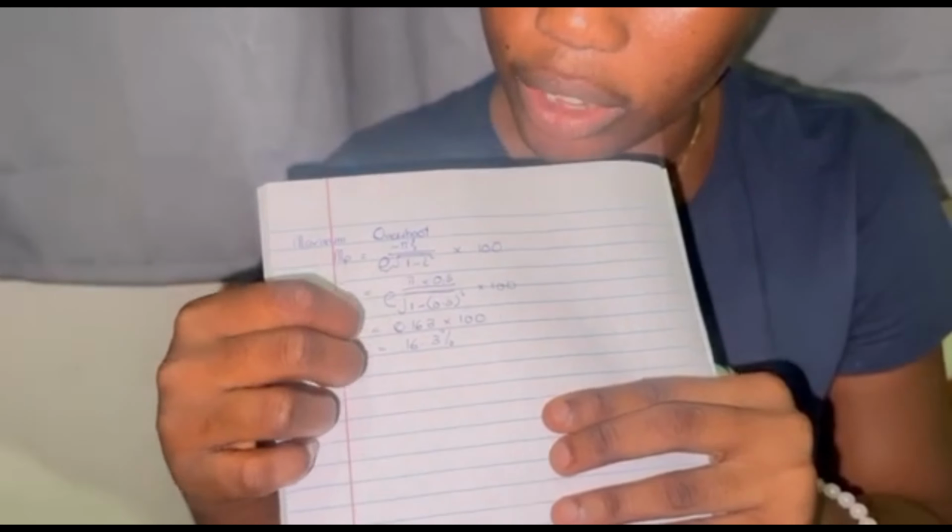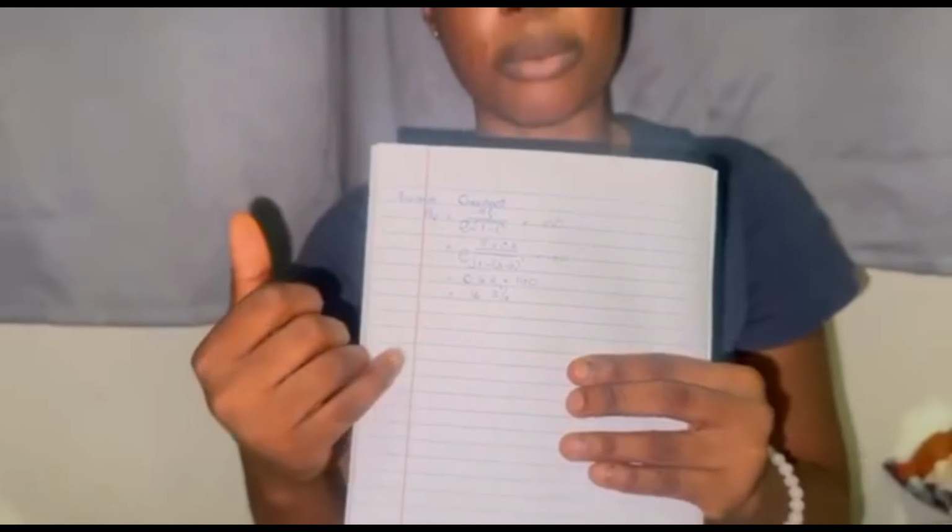I'll be taking you through the last question, that is finding the maximum overshoot. We have a formula: MP is equal to e raised to the power minus pi zeta over square root of 1 minus zeta squared, times 100. Zeta is the damping ratio, and in this question zeta was given as 0.5. So as you can see, we fixed the 0.5 into the formula, where we got our answer to be 16.3%. This means that the system output can exceed the final steady state by about 16.3% before finally settling back to its stable value.